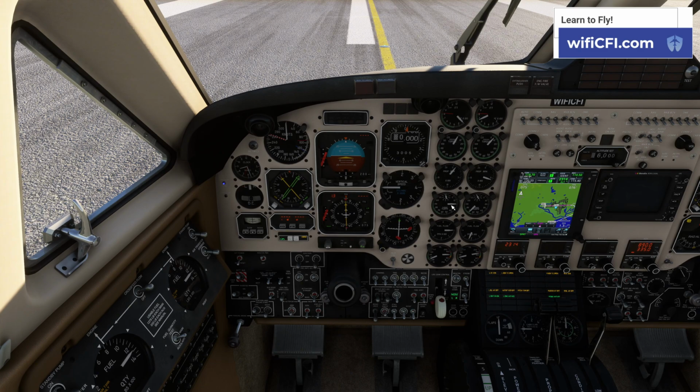It's coming up, stabilized. We'll go ahead and introduce some fuel with our condition lever, fuel flow, ITT we're watching here. I'm going to make sure it doesn't get too hot. Oh, you can see it starting to roll back. All the rest of the engine instruments are looking good in the green. Over 50% on our N1. Let's go and get that guy off, our starter off.